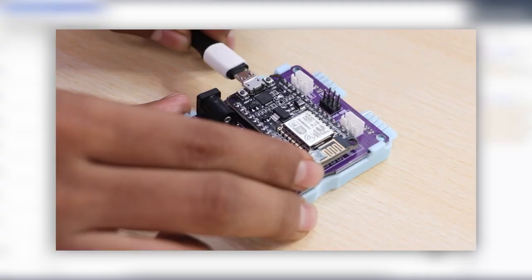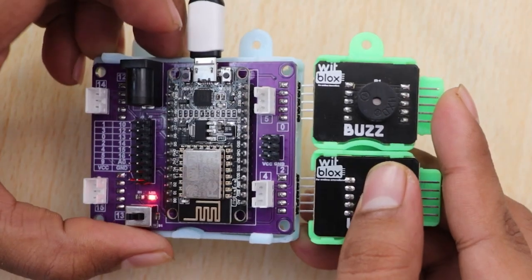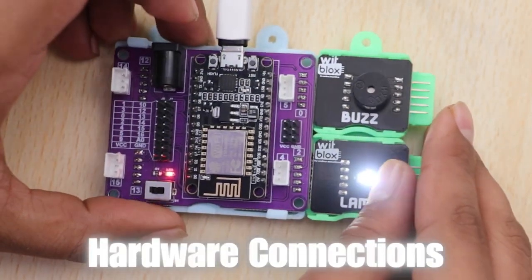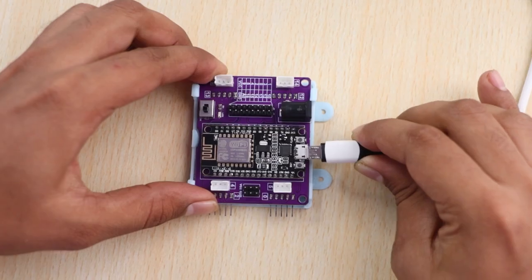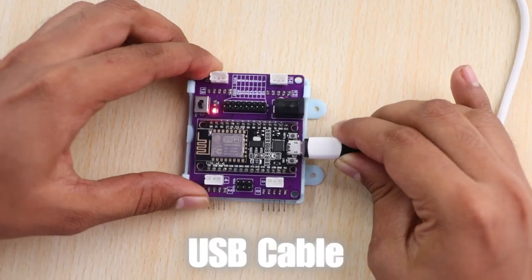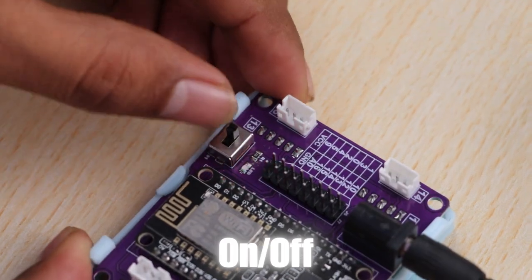In the previous video, we saw how to connect our WitPro to our computer. In this video, we will learn how to use our WitPro Blox to do hardware connections and control real hardware using our code. First, let's understand the power supply part. Supplying power to the WitPro can be done either through the USB cable or to the 9V battery via the DC jack. There is also an on-off switch to control the power supply.